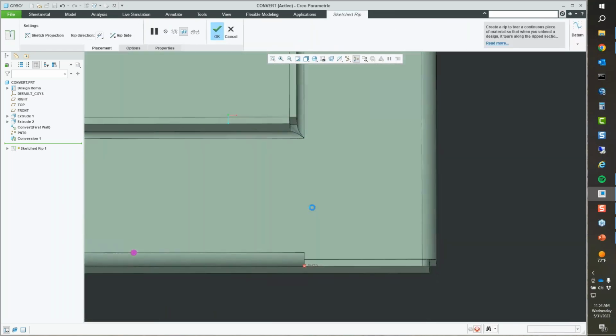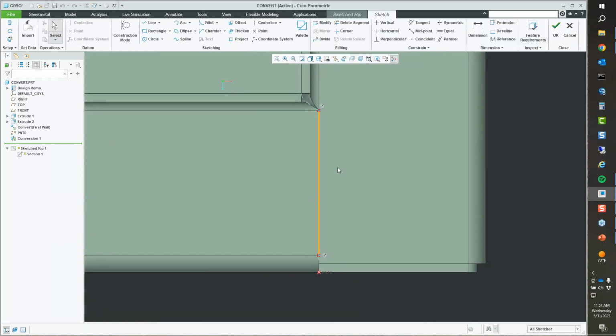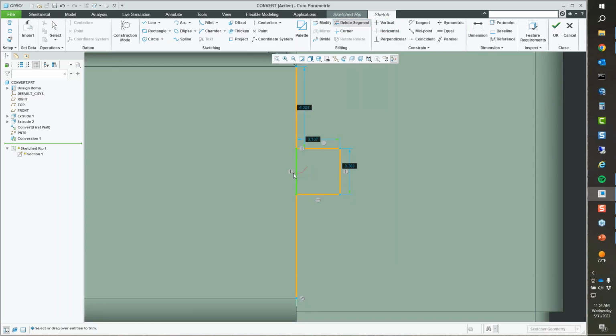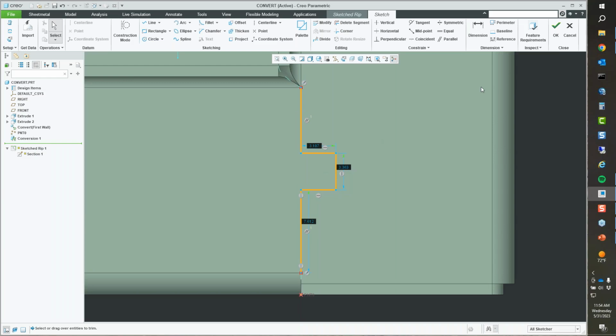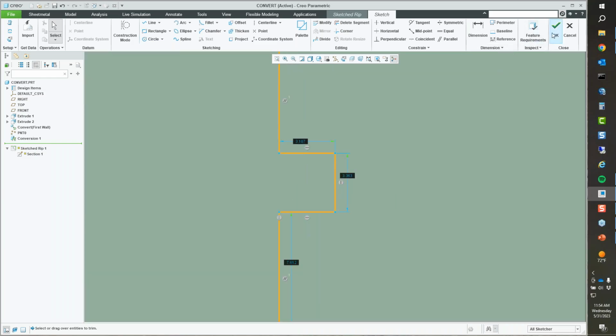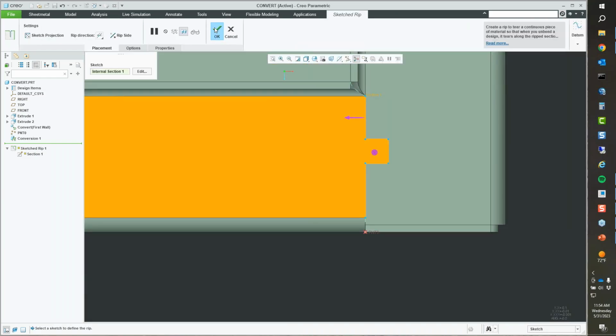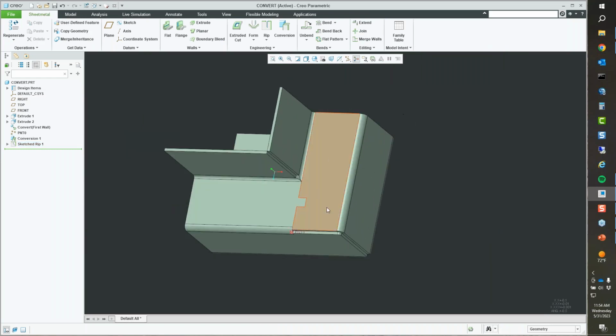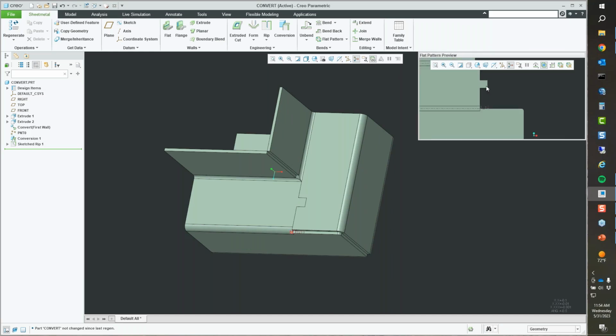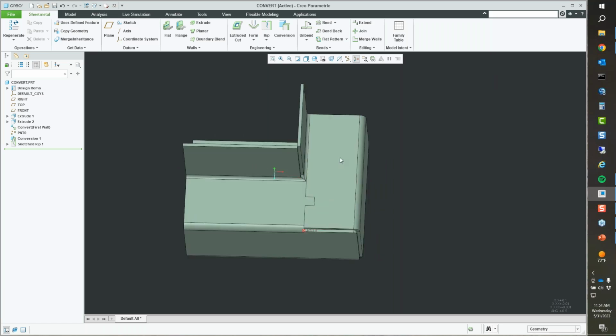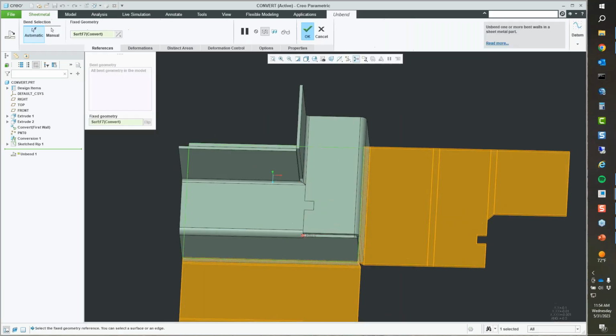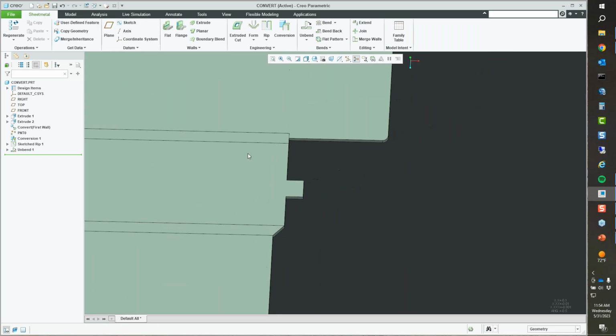But what I want to do is put in a target, right? So some way for the guys to know as they're building this that they're fitting things together. So I'm going to go in and put a little keyed access to this, and I can add my rounds here too. But what I'm going to do with that is a little bit different, right? Because there's my key, and we can look at our connections. I want to give myself a little bit of relief in there, so I'm going to unbend everything. And then I'm just going to go in and add some rounds.